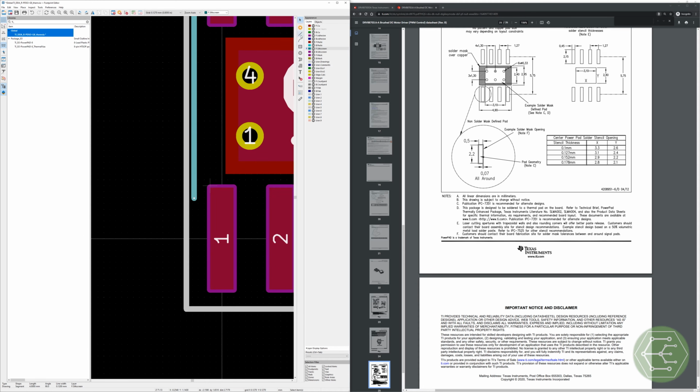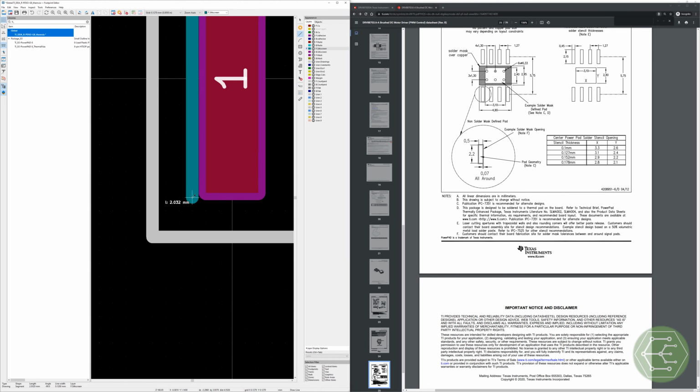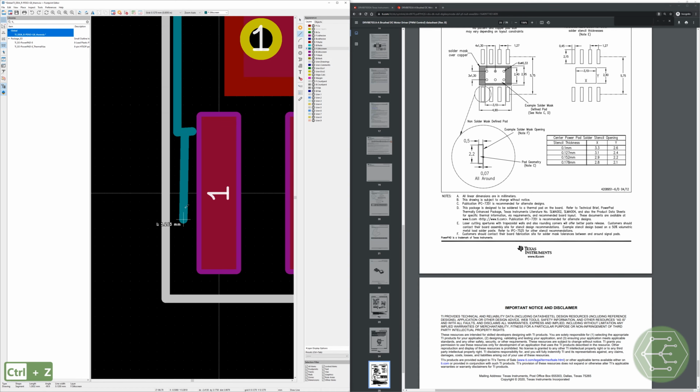So there it is. And to designate pin 1, I'll just go with the standard notation for KiCad libraries, which that might be too close. I might need to bump that out a little more. 0.595.